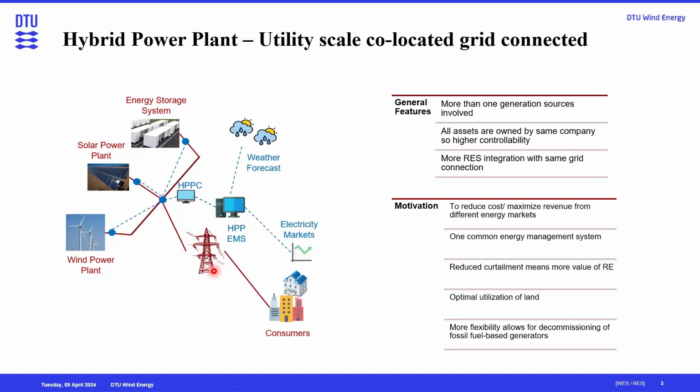So they are trying to maximize the value for their own power plant, which may not always be in tandem with the energy system minimizing cost. And this is understandable as well, right? The typical paradigm in wind plant design or solar plant design for that matter is to minimize the cost, so to provide the cheapest electricity. But if you want to design a hybrid power plant with minimization of cost as an objective, then you will never put in an energy storage system, because the energy storage system does not generate energy.